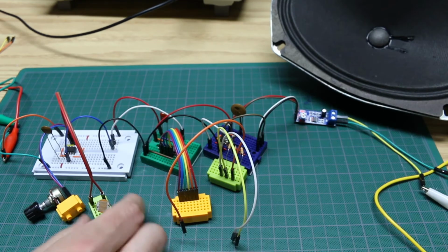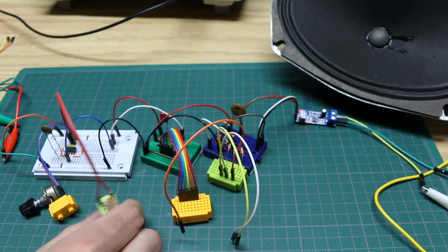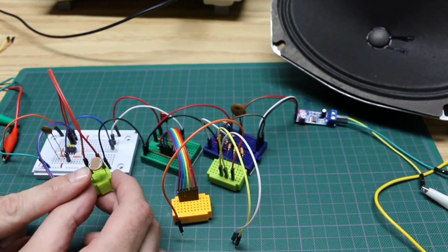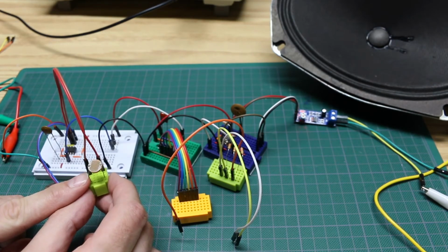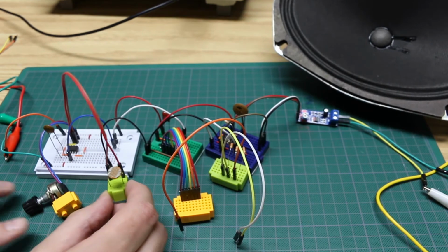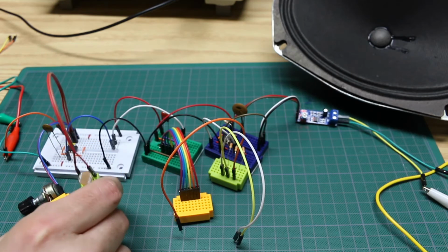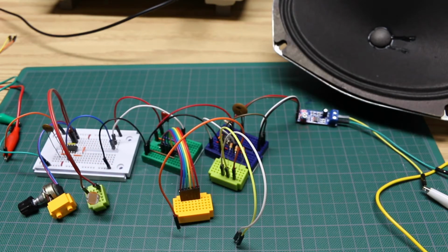So basically, I don't even think we need the potentiometer if this is in parallel. I think this is a 100K pot, right? And this is maybe, I don't know, 30-something K average. In parallel with 100K makes it negligible. So it's just this doing the work. So already I can see the potential for making weird sound effects and having things interact a certain way, more than just a boring keyboard that happens to track itself with octaves.